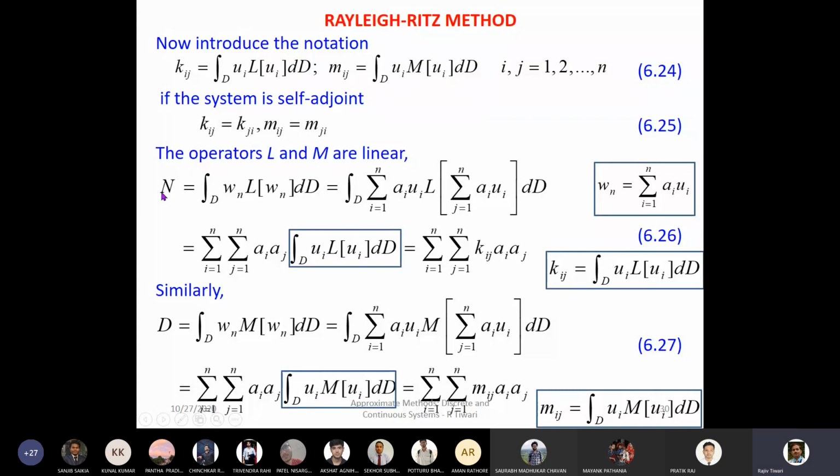So the n which we defined earlier was this. In the very first slide, when we started with the Rayleigh-Ritz method, we defined the L numerator part as this. Now we are substituting the W, which we have chosen as a series combination of the comparison functions multiplied by the constants. This is the term representing Wn, the comparison function multiplied by the constant, with integration and summation.